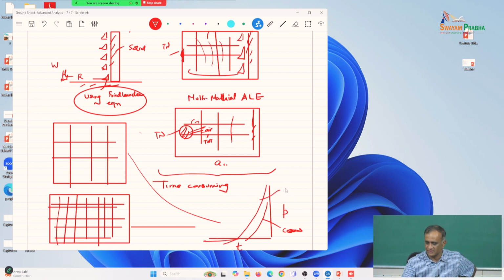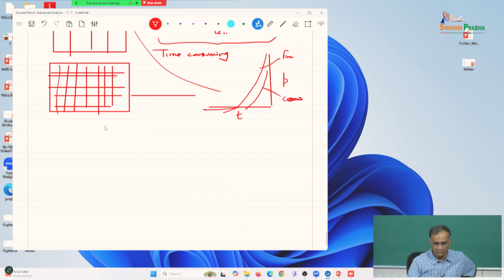I am just giving some examples. So, the pressure distributions are different for different cases. You will have to see which mesh size works well. Most people ask this question, have you done a mesh sensitivity analysis, to check for an ideal mesh size?